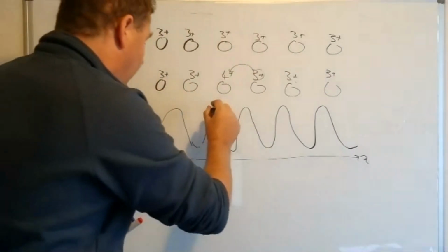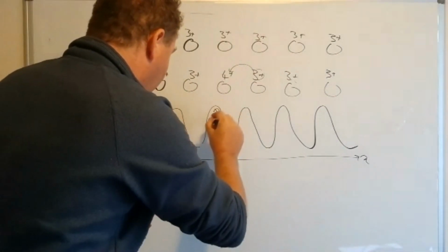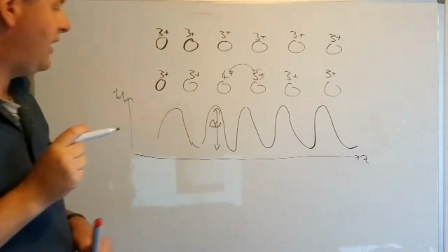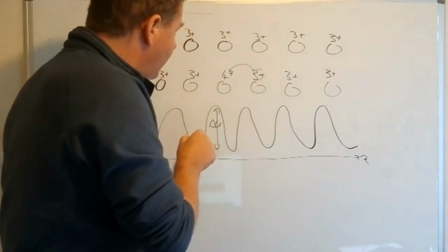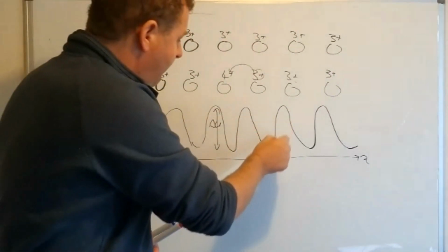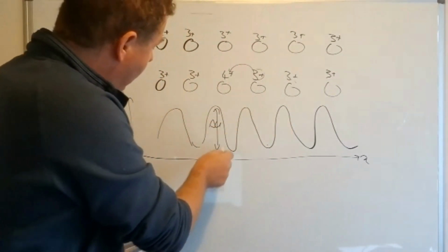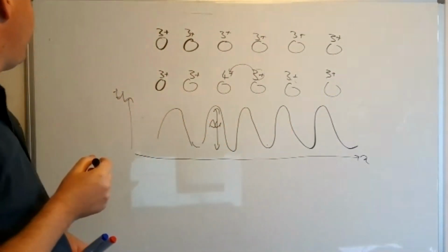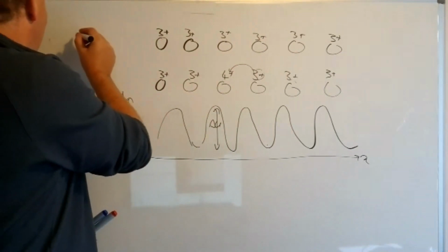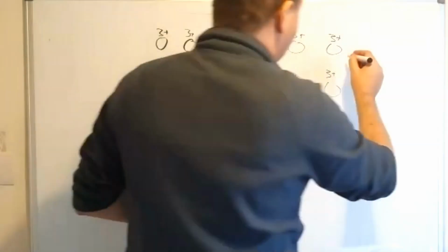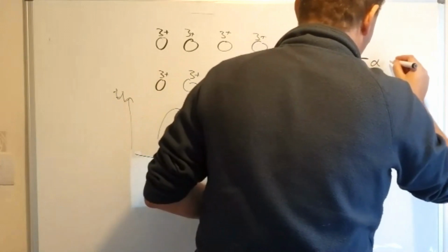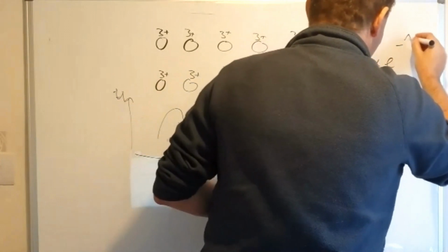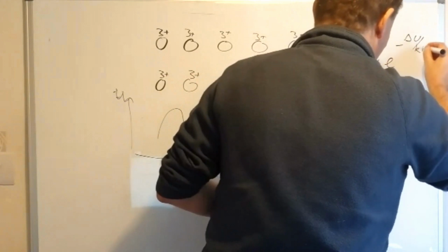And what you're having here is an energy barrier delta U. And so the probability that you get an electron from here to here is going to go as some kind of attempt frequency times an exponential energy barrier involving delta U. And so the conductivity sigma is going to be proportional to e to the minus delta U over kT.